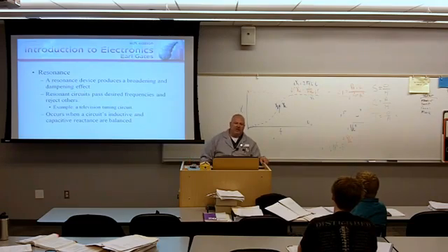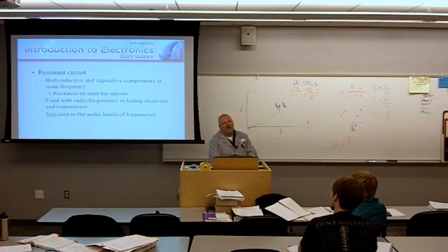So it occurs when the circuit's inductive and capacitive reactance are balanced or equal. We use this inside tuning circuits, inside televisions, inside radios. In a resonant circuit, both the inductive and capacitive components are at the same frequency, the frequency of resonance. Reactances are equal but opposite, used with radio frequencies and tuning receivers and transmitters.